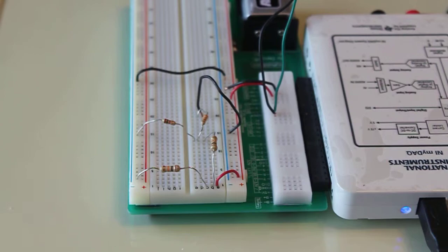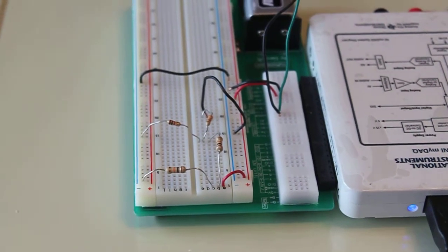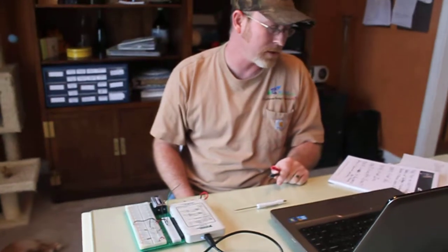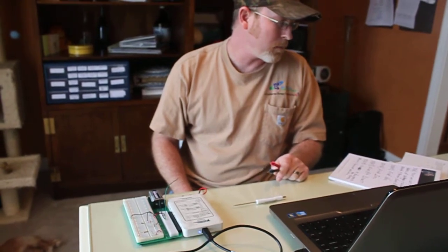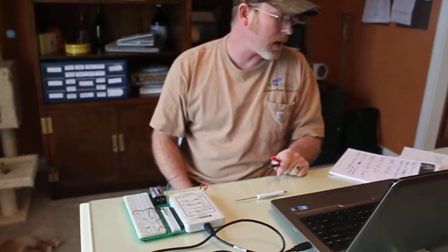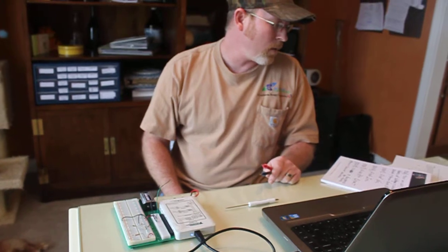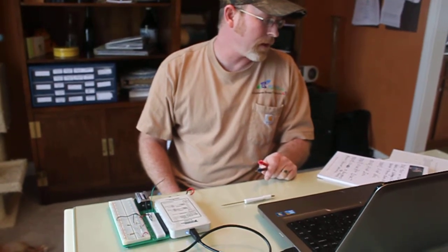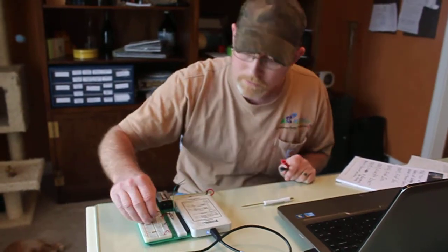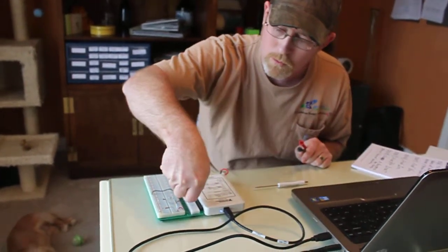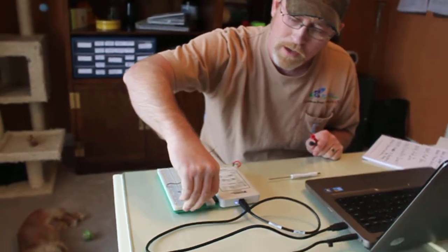Now we can take both of those and figure our Thevenin equivalent by just dividing our voltage by our short circuit amperage, and that'll give us our Thevenin. But there's another step in here that the lab is wanting us to perform, which is finding the Thevenin equivalent resistance directly. And the way we do that is we take the voltage source out of the picture.